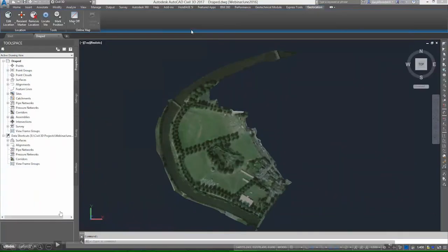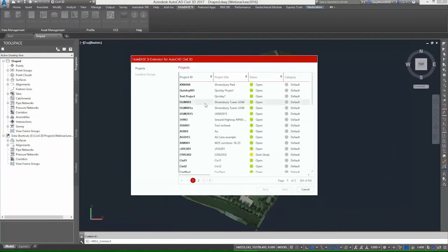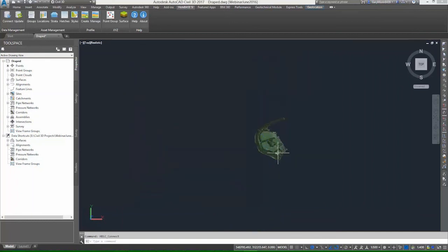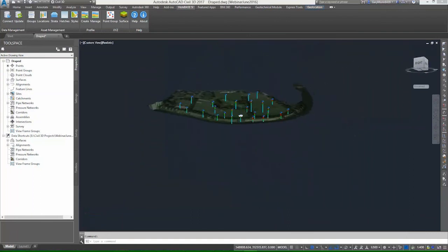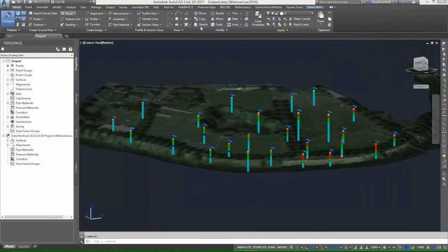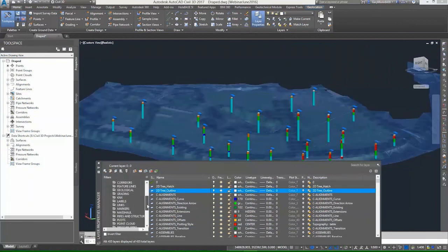In a similar scenario, we've got this right here. If we can pull the data quickly into AutoCAD Civil, then we can start using it to visualize and understand what's going on around the site. So here I've got a ground survey and I've draped an aerial image over the top of it. But look now, across my site I can very quickly see where I've got different geologies. And as we pull the data in, we've put it onto different layers.